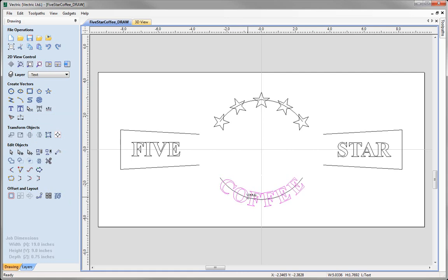If you want to increase the space between letters, you need to hold the Shift key down and then click with the left mouse button. So just click in between, so it looks visually to your eye that they're equally spaced. And when we're happy with that, we can simply come out of that mode by pressing Escape on the keyboard.